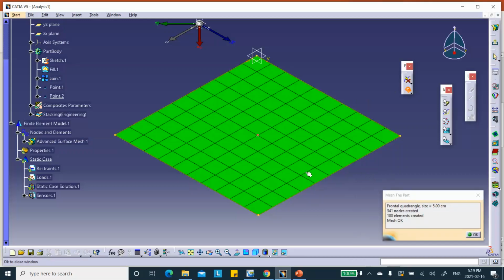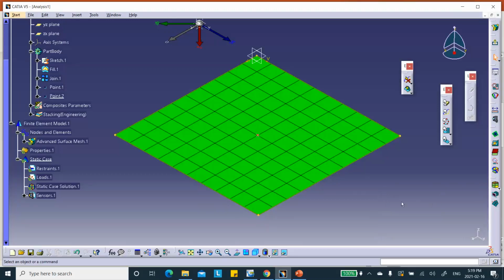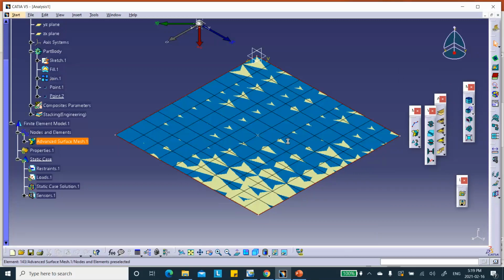All right. My point is that with this trick, it doesn't matter how ugly the shape of this mesh is. You need a trick to make sure that the point that you want to apply load at is actually a node. And I tried a few sizes. You notice that they get ugly meshes in this area. But if you don't do this, there's no way you can apply a force in the middle. Okay. All right. Good. So exit. All right. And we're done here.